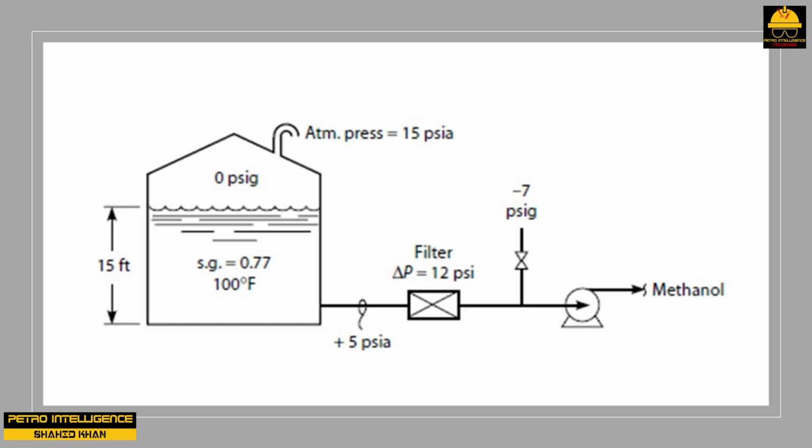Pump suction under vacuum. Liquids in storage tanks are almost always subcooled. This is so because otherwise the ambient vapor losses from the tank's vent would be excessive. This creates the potential for a negative pump suction pressure. For example, the pump shown in picture is suffering from a partially plugged inline suction filter.